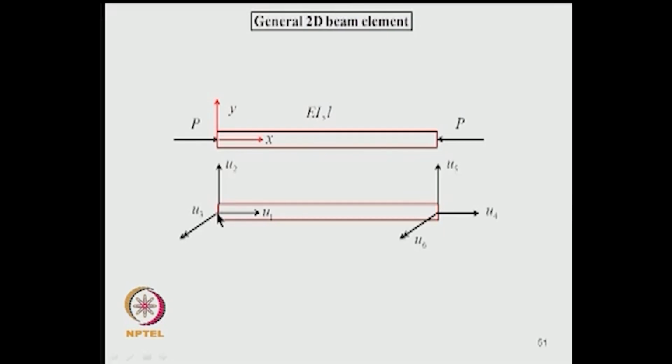But when we come to doing the same problem for geometric stiffness analysis, that is not so. It is not just that the axial loads interact with bending, the other interactions can also take place. The initial state of stress is multi-axial. So, in the initial state of stress there are torques, there are axial stresses, there are 2 bending moments.